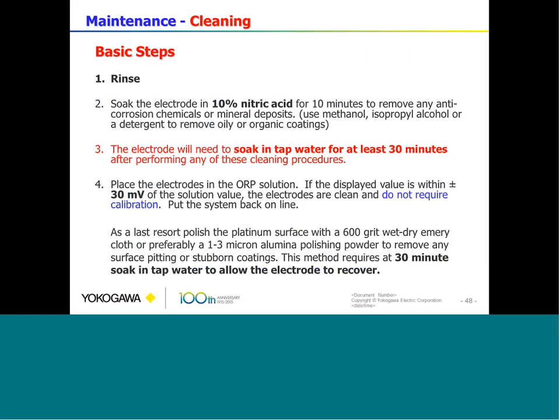The cleaning is similar to pH. Here we rinse everything off, obviously. We put it in nitric acid and let it soak for 10 minutes to remove whatever's on it, mineral deposits and corrosion chemicals. If it happens to be oily, you can use methanol or isopropyl alcohol to clean it off.